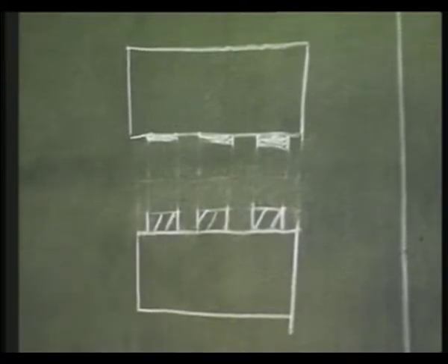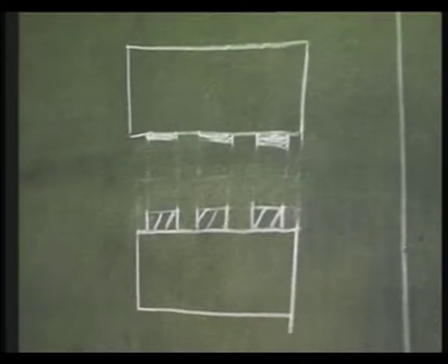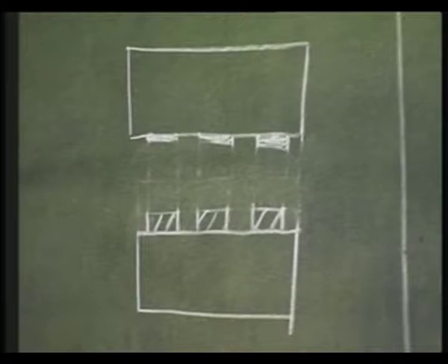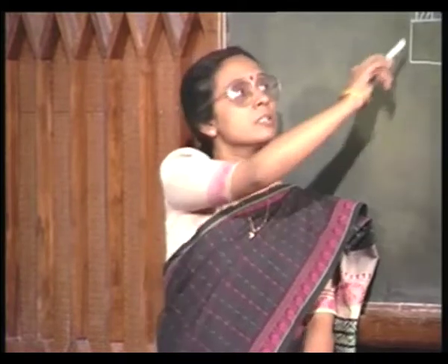The pattern on the semiconductor has a 1:1 correspondence to the mask pattern. So, this type of resist is called a positive resist. The pattern of the mask and the pattern on the semiconductor is identical. This is a positive resist where the exposed resist gets softened.